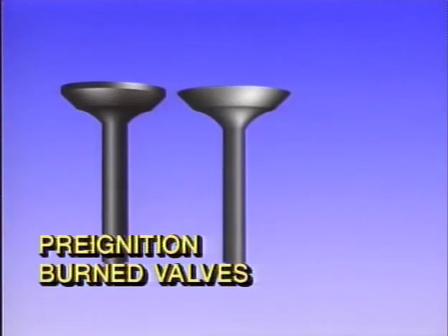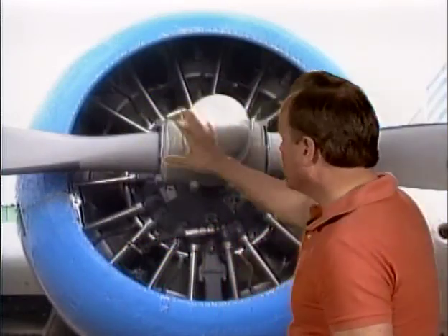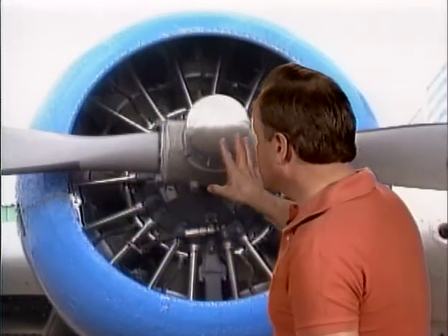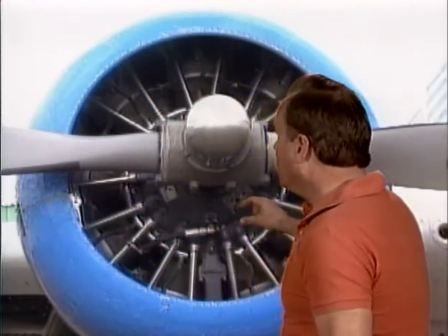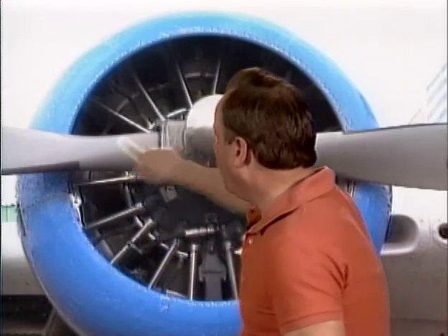All right, let's talk about oil. Oil is pretty important, you know that. So let's assume that you're overhauling an engine with a dry sump. By the way, a typical engine with a dry sump might be a radial engine. The FAA wants you to know before you run this engine, it'd be a good idea to pre-oil that engine. How do you pre-oil the engine? Well, you take the oil lines and pump oil into the engine to make sure that you have oil all throughout the engine.